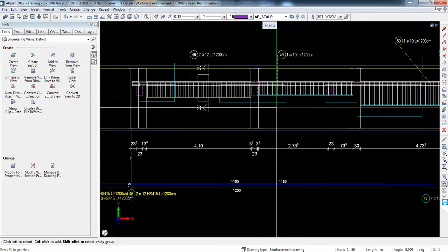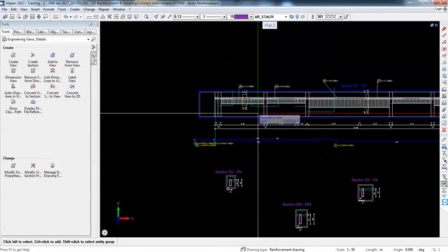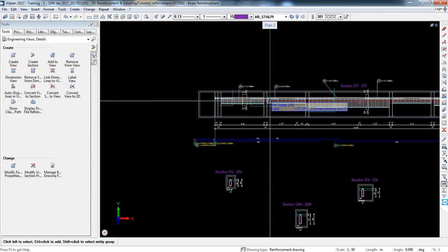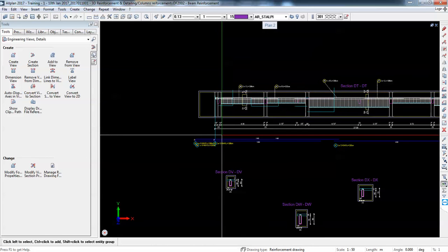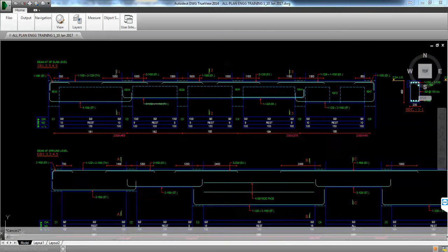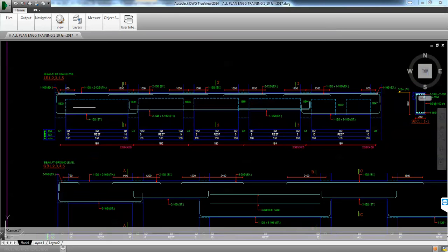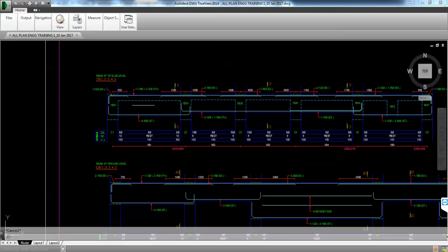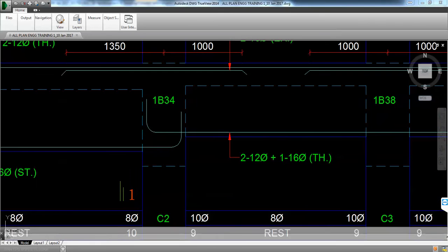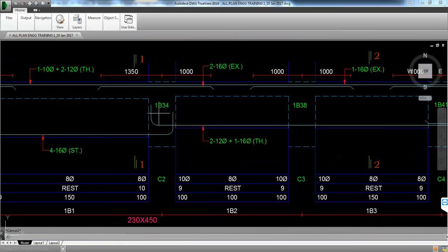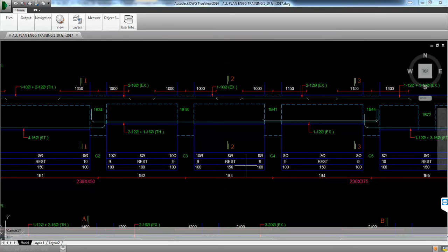And on the lower side, I can either mirror the top bars, but it's not a good idea, as always the overlapping of the top bars is opposite to the overlapping of the lower bars, as the bending moment differs. So I will need to create all these bars. You want this hook, so you want to anchor within a beam, right? As in the example. Okay, this is how we'll do also.